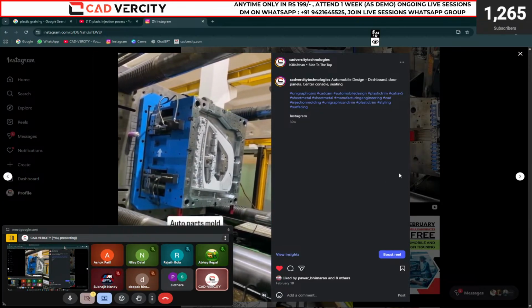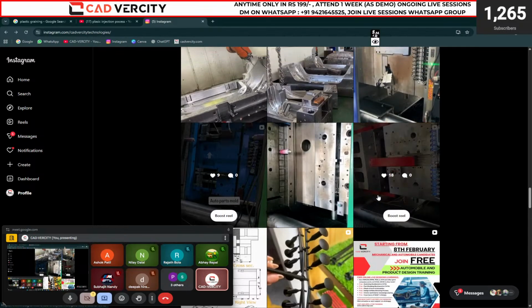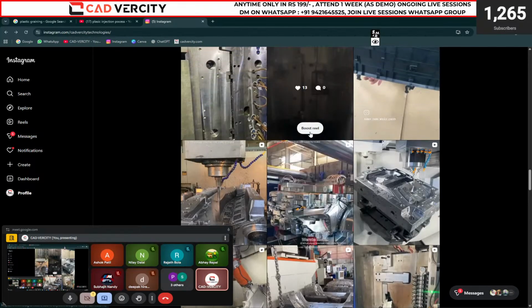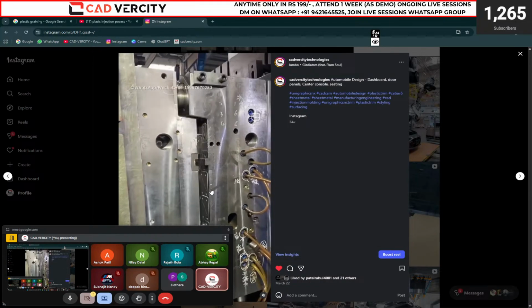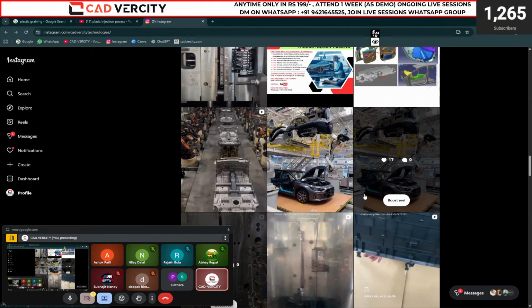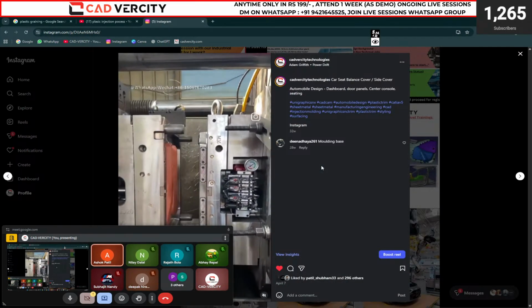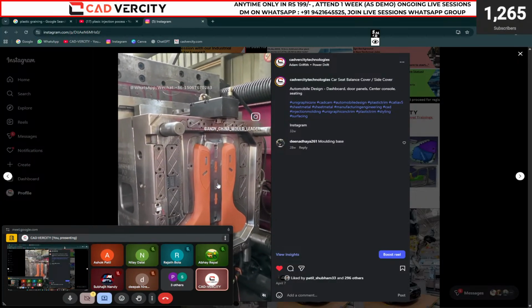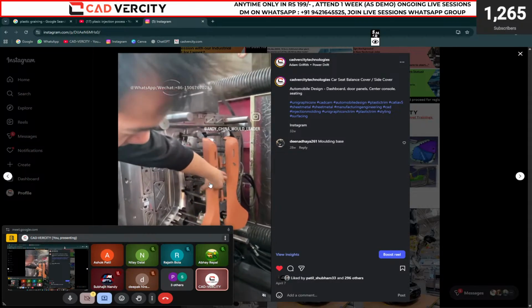Door panel. See, the pushing elements, the ejector pins, from the A side is not possible, because the part will be locked in the tool because of B side features. So we will have ejector pins from the B side which will push the part, which will help to eject that part from the tool. I think we have seen this. See the side covers. Remember, we did a close volume of this. Yes, sir.